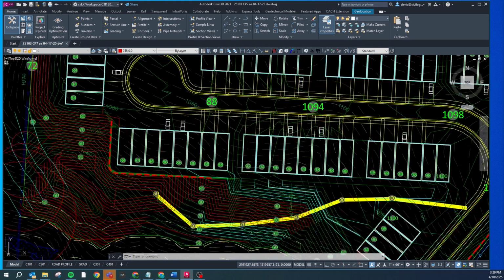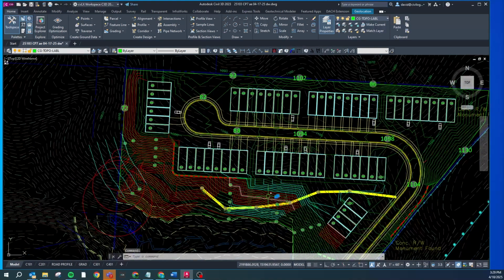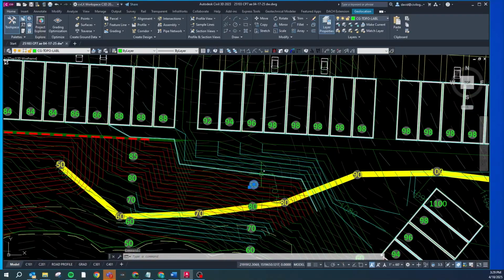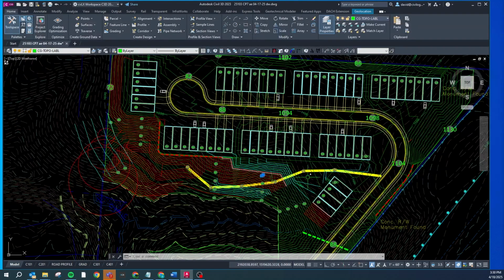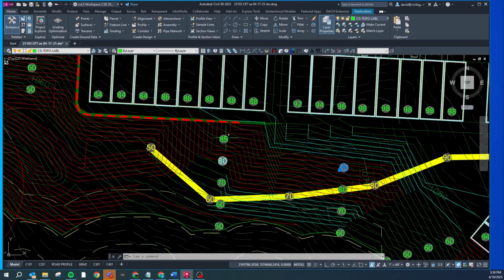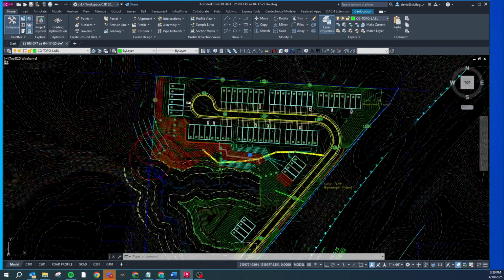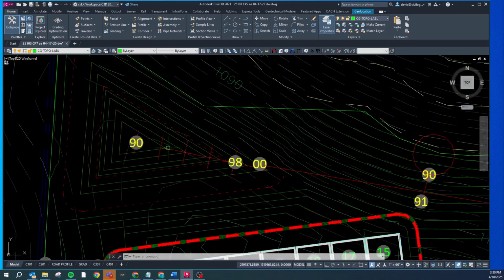And then we can simply add these spots to assign an elevation based on the text that we've typed in there by using the BELEV command, BELEV. And once those blocks have elevations, we can add them to the surface and modify our surface using these blocks. Then we can just spit out contours from that surface, and it's going to show you which direction all these contour lines go.